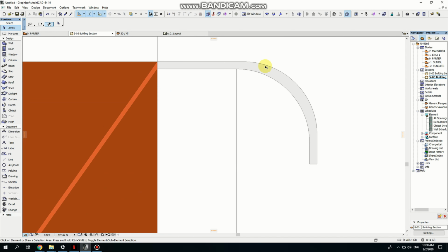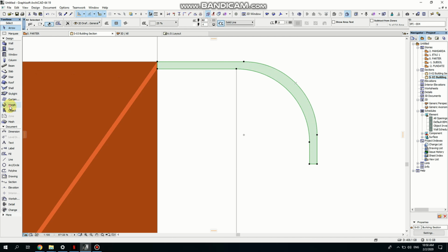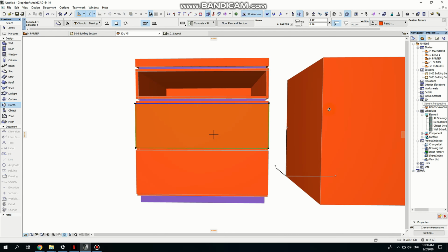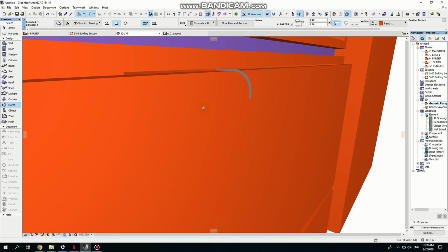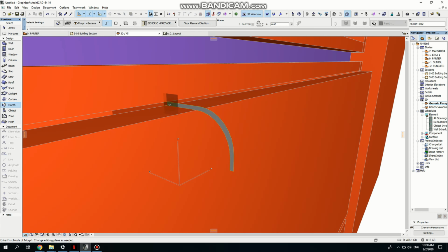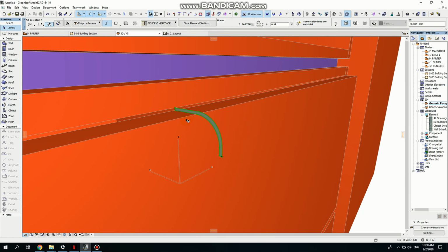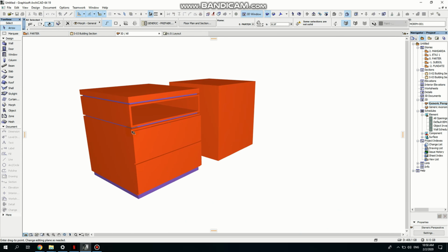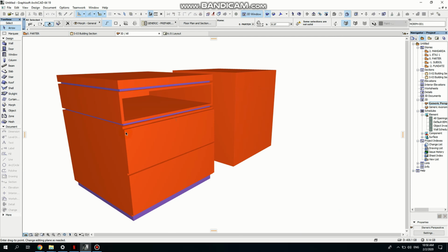Because I have the fill here, I'm going to use a morph. So with the fill selected, go to morph, hold space key, and click inside, and you'll have the shape of the handle. I'm generating the view because I want to see. This one has no thickness, and I'm going to drag it, so Control D, and I'm going to drag it to the beginning of my module.